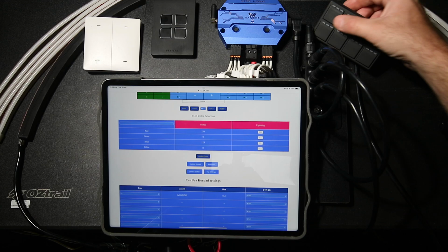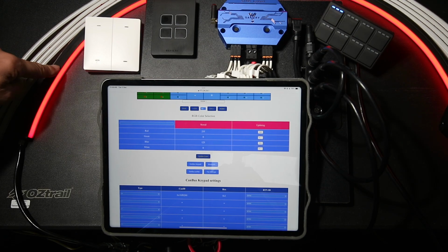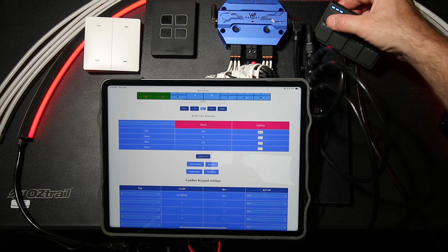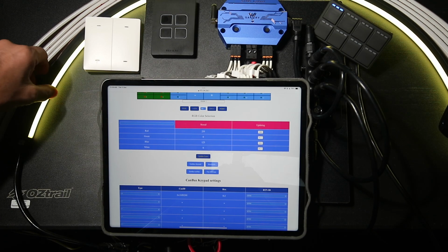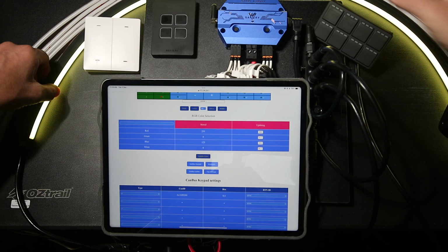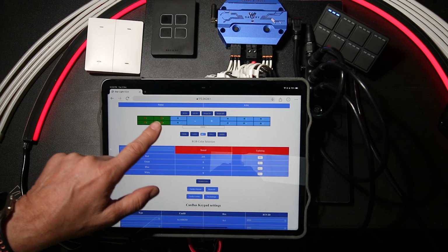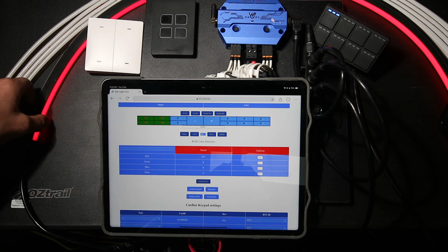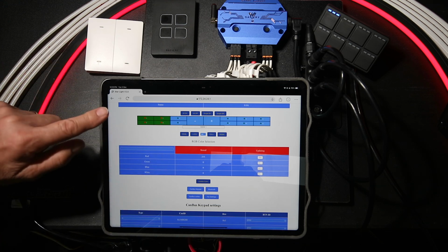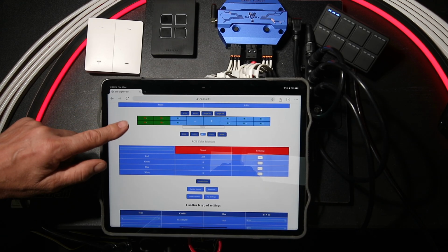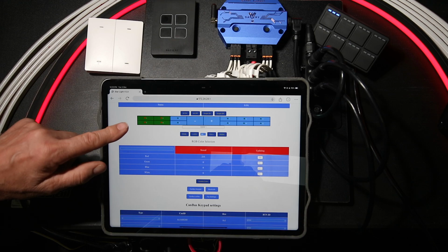Let's press button 1. As we press that, the color that we're getting here is the color that we've updated. Let's do the double press. When we double press, we go back to a secondary color here. We press one more time, and we're back to the red. One more time, double press. So in the RGBW, you can see all 4 channels here are active, and as we do the double press, it goes between the red color to the white color and back again. We always have the RGB channel wired up so that you get a choice of 2 colors.